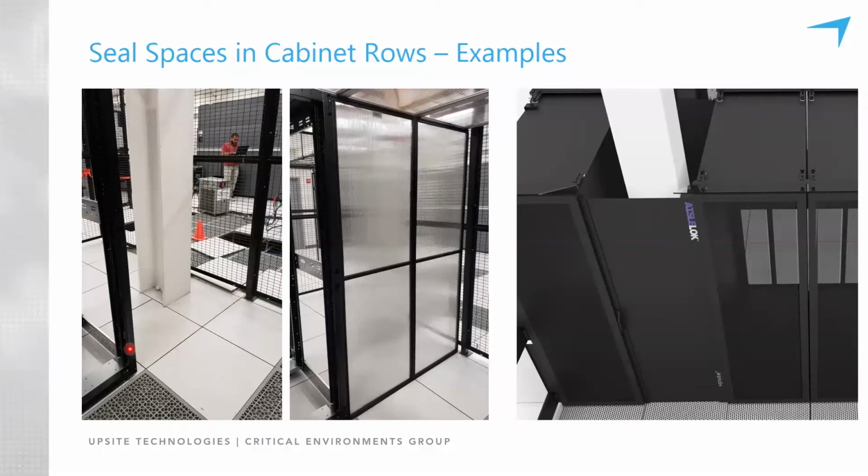So what the customer asked us to do, they required vertical rigid panels, and instead of building one that spans 48 inches wide and the height of the cabinet, there's two of them side by side that are kind of attached to the adjacent panel. And the first one can be removed because this is that roll-in consideration I mentioned earlier, where they would like to in the future be able to roll another cabinet in there, so they can just take this panel, the left panel, out, put the cabinet in, and reattach the right panel to the end of the cabinet.